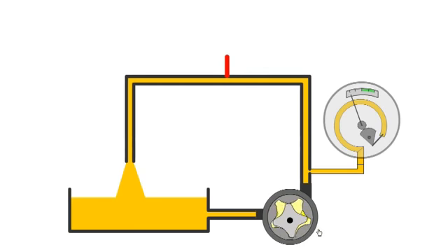We use a Bourdon pressure gauge to indicate oil pressure. When pressure in the tube increases, it tends to straighten, and this change in dimensions is amplified by the linkage and gears and displayed by the pointer on the dial. If we close the valve, the flow of oil is restricted and we start to build pressure. If we close the valve further, we see another increase in pressure.